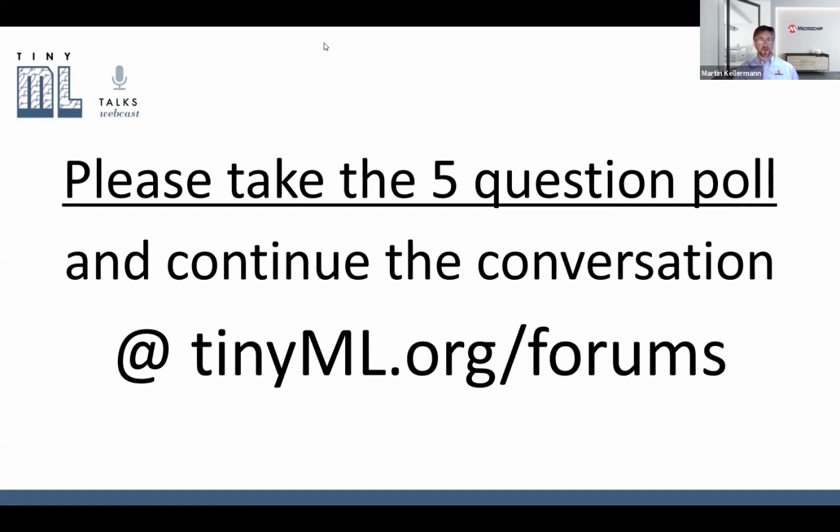Yes, so that is definitely an option. The only reason why I did it the other way was personal laziness. I just wanted to do it that way, and it was pretty straightforward to hook it up. But yes, if you want to go for an optimized solution, then that is also an option. You would then instantiate just an SPI IP core or create it yourself, and interface to the outside, to the sensor, to the pre-processing, and bring the data into the TinyML.